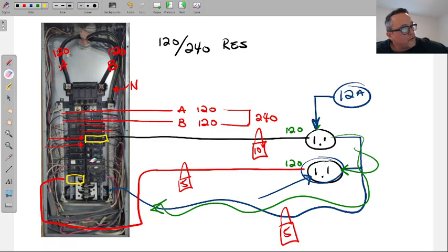Measure the amperage on the neutral. Now here's the thing, I would never think of that. I would get shocked by that neutral. So that's a code violation. It is a code violation, and it is also maybe a grandfathered-in situation, where back in the day they used to do it, now they don't. And so you have this from old circuits that can come back and bite you somewhere.